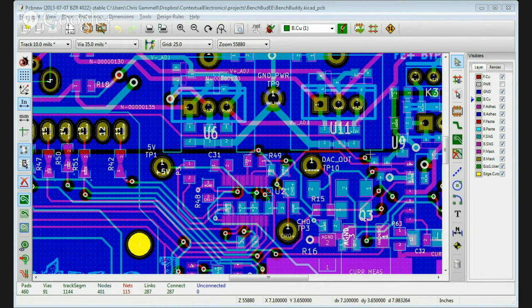And then from there, I could turn the screen off and show here. We still have to test the secondary FET, where we disengage the sense resistor and then actually drive it as a voltage output. That will be interesting as well, because that'll interplay with the PTC on the back, the TH5, since that'll actually be our main limiting current thing there.